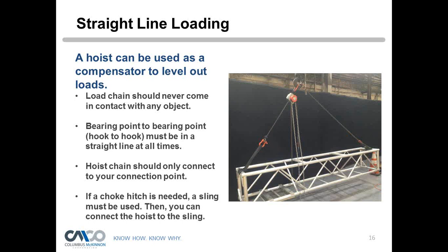The answer to the question is yes, it can be done. And you would do the same pre-operational inspection with the lever hoist and make it safe, and the same criteria would apply. That straight line pull, and you don't want to connect the chain of the lever hoist directly to the connections. You want to use the proper connecting method. Okay, thanks.